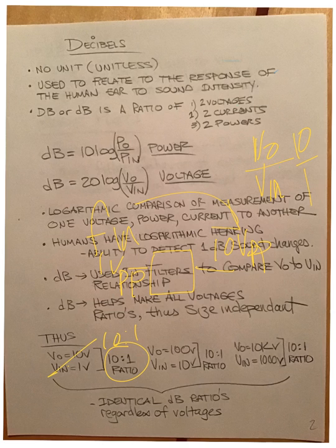If I put in 10 volts versus 1 volt, and I get a ratio of 10 to 1, and I decide to go with 100 volts and 10 volts, coming out is 100, going in is 10, it's still a 10 to 1. If I decide to feed the filter 10k volts and my input is only 1,000, that's still a 10 to 1. The dB ratios don't care what the actual voltages are, only that their ratios are identical.